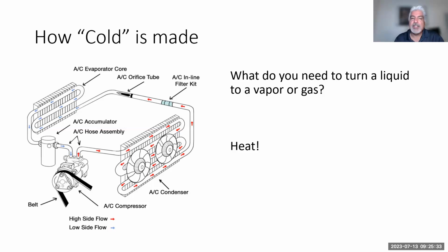So therefore, what you're going to see is that you can buy and install on different AC systems filter kits. There are AC inline filters. Just Google it and search them. You're going to see that many vendors sell filters, whether it be a pancake style, a big old flat one, or the sausage style. There are many different styles. Believe it or not, you can cut a line and actually put in a filter kit in the event you're trying to protect the compressor, because we have seen cases where guys have replaced compressors several times because there was still contamination, such as metal or other desiccant material, in the system that's just destroying especially the compressor itself.